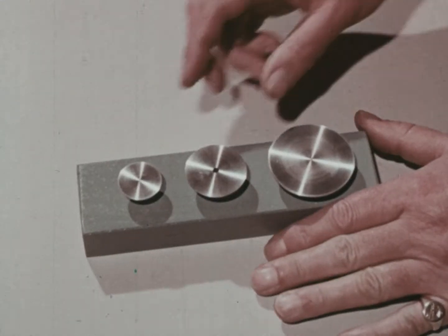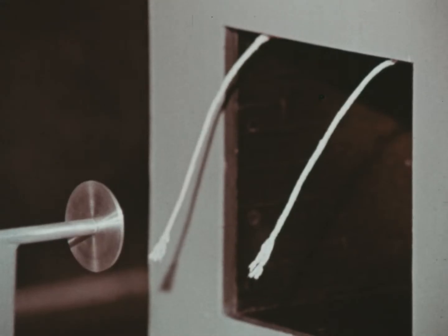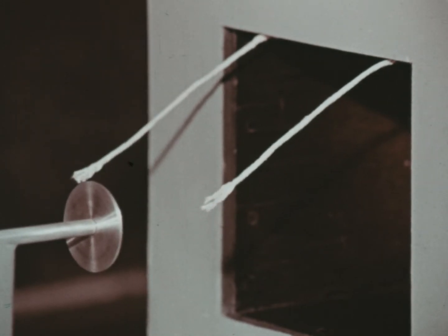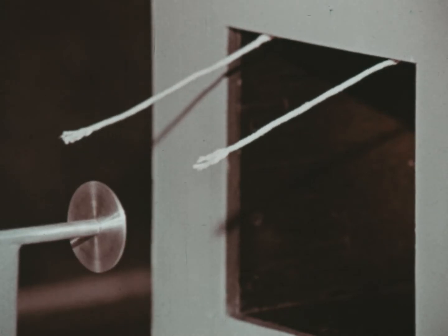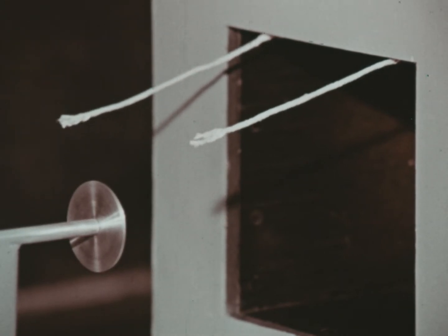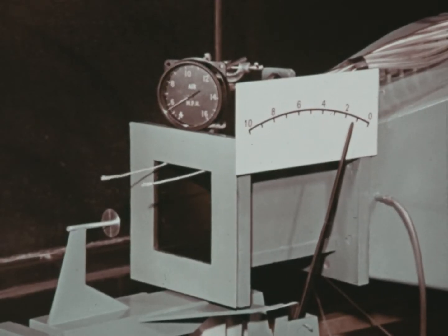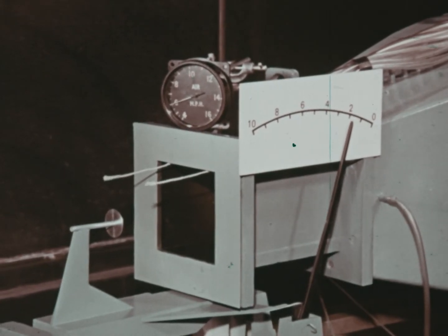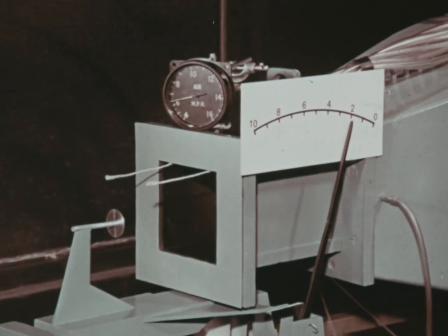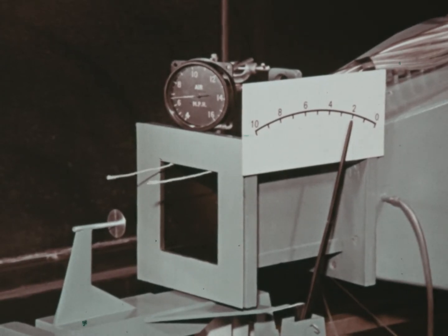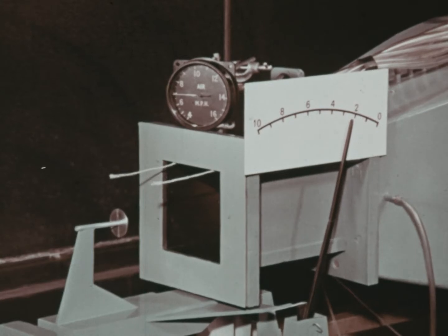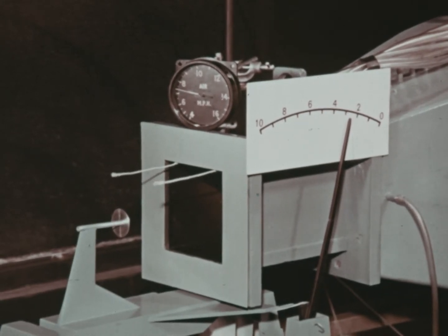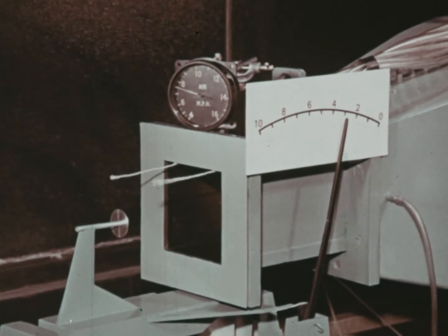Take a disc of given area and put it in the mouth of an open wind tunnel. Mount the disc on a sprung slide attached to the indicator arm of a calibrated gauge. The airspeed in the tunnel is measured by an airspeed indicator. Notice first that as the speed increases, so does the drag. In fact, the drag increases as the square of speed.